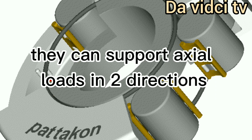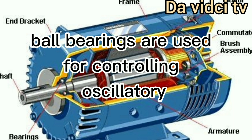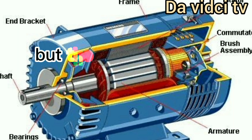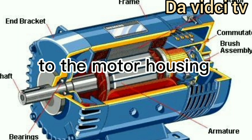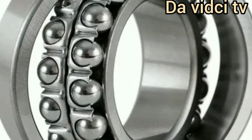They can support axial loads in two directions besides radial loads. Ball bearings are used for controlling oscillatory and rotational motion. For example, in electrical motors where the shaft is free to rotate but the motor housing is not, ball bearings are used to connect the shaft to the motor housing. Depending on the application, different types of ball bearings are available to choose from.